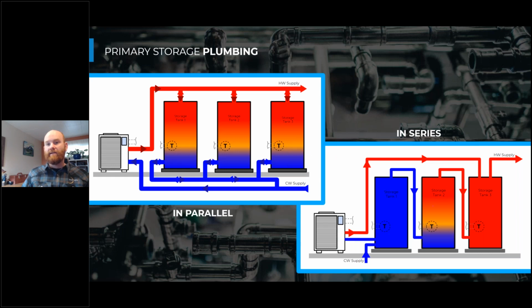In series, we're essentially going to connect the top of one tank to the bottom of the other. And what this does is it takes this tank and puts it on top of this one. And so that basically stretches our thermal volume vertically, and we can get a lot of stratification. And that's one thing that we discuss in our engineering deep dives: when the in-series storage tank design really makes sense, what some of the great advantages are for it, either from a thermal stratification standpoint or controls, and how to make sure that you're not going to run into any issues.